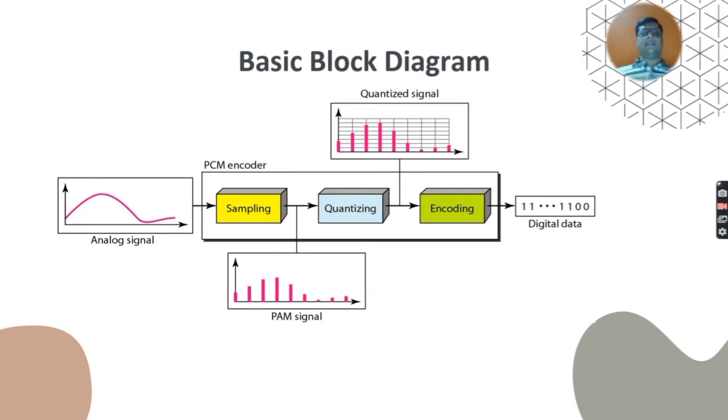And you can see below, it is called PAM. It is a pulse amplitude modulated signal, and we can also see the sampled signal. Now once this pulse is identified, we need to quantize the sample. When we are quantizing, we are compacting the time period and identifying only the discrete values. Remember that the sampling and quantizing steps, if I combine them, are called discretization.